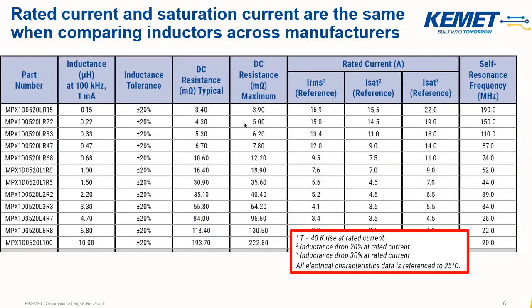And going off of the data sheet, you think vendor B is a better component. But if you dig into the data sheet, factoring in allowable temperature rise, vendor B may have a much higher allowable temperature rise than vendor A, but vendor B also has a lower operating temperature than vendor A.